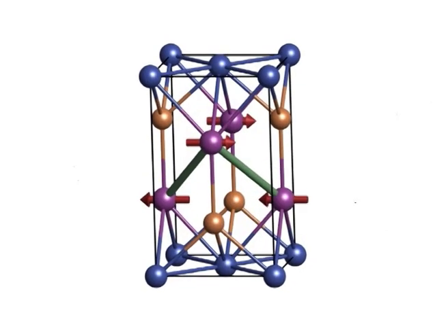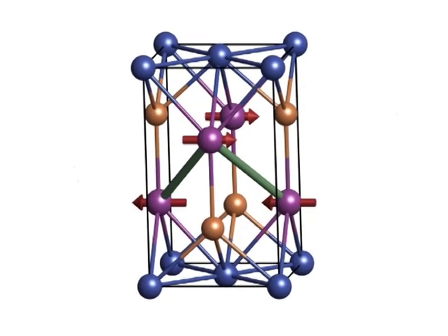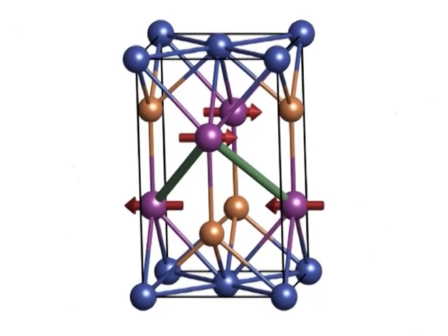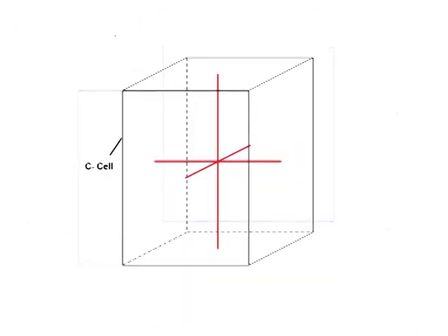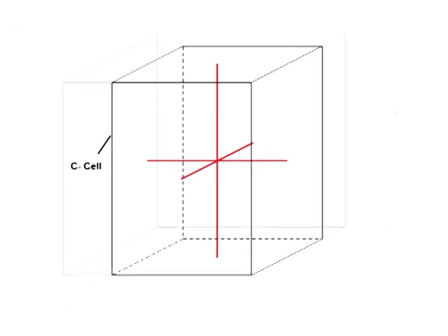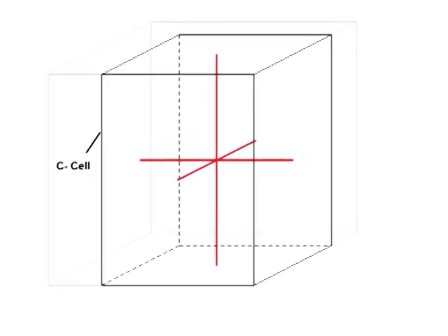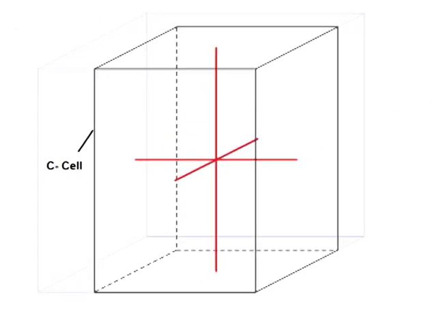3. The fact that a unit cell meets the symmetry requirements of the crystal system does not guarantee its inclusion within the crystal system. This could result if the lattice it generated could be equally well represented by a unit cell type which is already included within the crystal system. The C-type cell for the tetragonal system, see figure 4, provides a good example. This figure 4 provides the C-type cell for the tetragonal system.